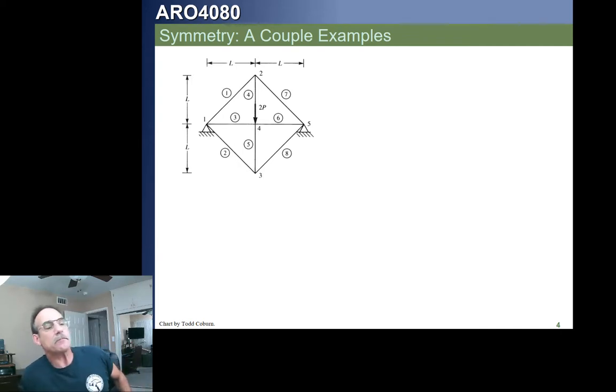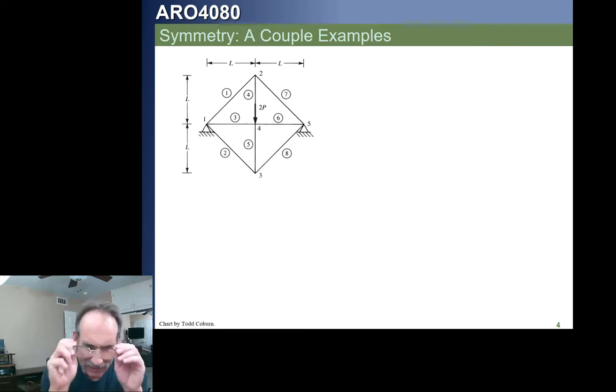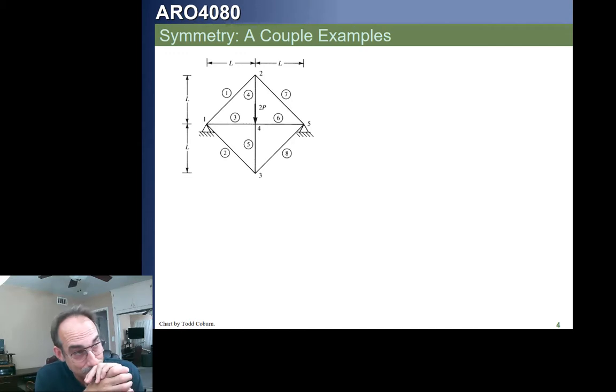So here we have a structure that we can go and analyze. This looks like we have truss elements. It looks like we have 1, 2, 3, 4, 5, 6, 7, 8 different members on a 2-node structure. And we can easily write a finite element model, or even write a system of matrices to solve this, writing the stiffness matrix for each. But if we're doing this by hand, we see this is going to be rather large. Since it's rather large, that's going to make it difficult to solve with our hand calculators.